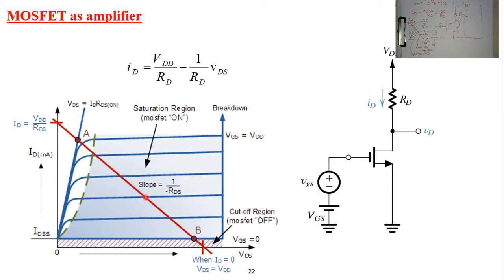Okay, so in order to investigate the impact of the AC source on this system, let's say, for example, that this is a 2 volt source. So what you are going to do here is go to the curve for VGS equal to 2 volts. Let me highlight it. Let's say this circle represents the operating point at VGS equals 2 volts, which is the intersection point between the load line and the curve where VGS is equal to 2.